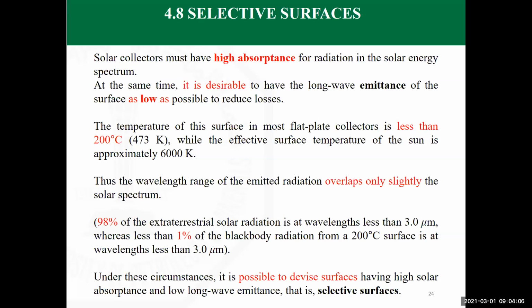If we are able to control the properties of the surface in terms of high temperature and low temperature applications, or short wavelength and long wavelength applications, then we can do something which is useful for us. What do we need? We need a solar collector that can absorb all the energy falling onto it and does not emit a big part of it. We need the emissivity to be low, but the absorptivity we need to be high.